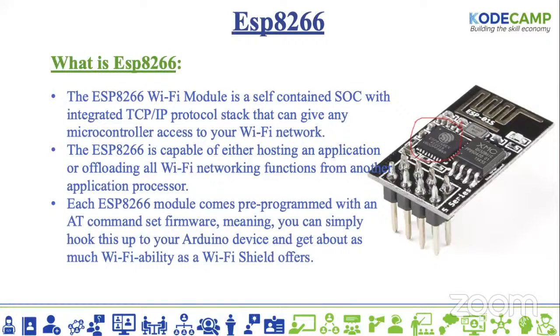Now the ESP8266 is capable of either hosting an application or offloading all Wi-Fi networking functions from another application processor. When I say it's capable of hosting an application, I mean that you can write your own program into it. If you're basically looking for some on and off switch programs, I don't think there is a need for an external microcontroller, except if you're dealing with a lot of GPIO pins.